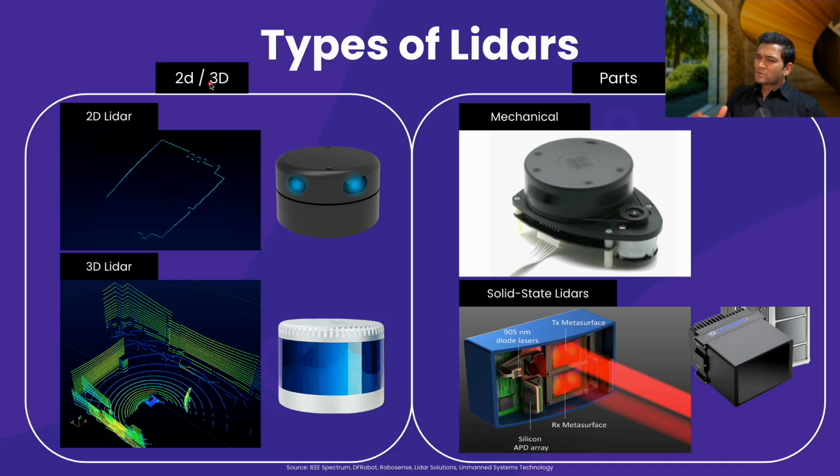So, remember from the previous section, we saw the sensor that emits a single beam of light and how it looks like. Now, imagine we put this single beam sensor with the sender and receiver on a motor, and this motor constantly rotates. What do you get? The distance that you will collect in such manner will look more like a line sweeping across the motor direction, much like this first image. To get a better intuitive sense, think of how an apartment floor plan looks like, right?